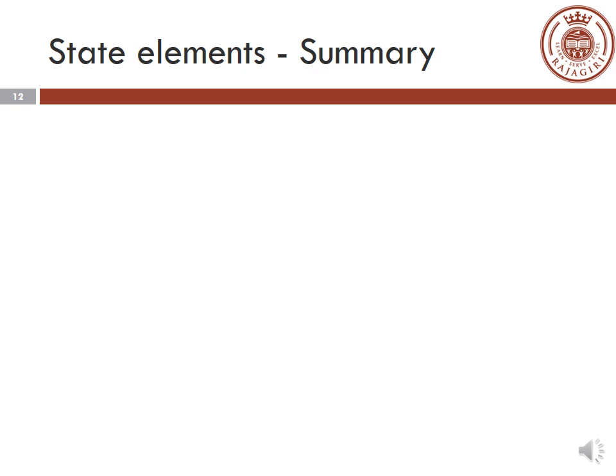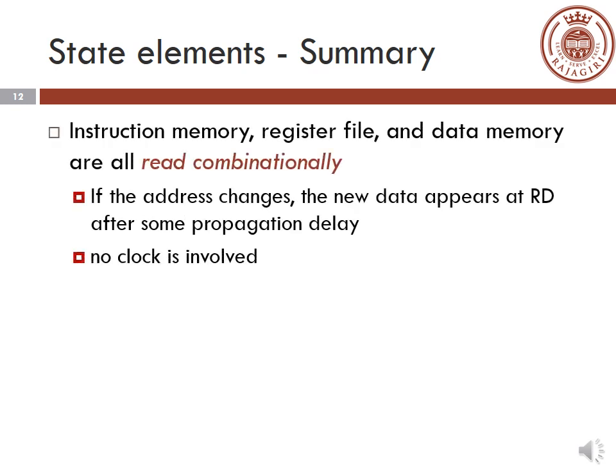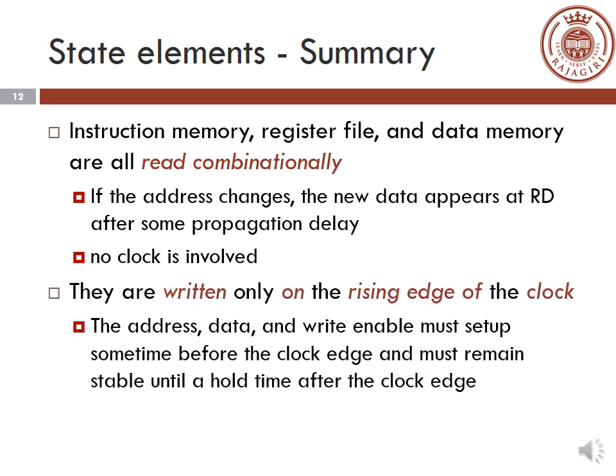Okay, so in summary, with respect to your state elements, the two important points that you need to understand are: for all the state elements, the write operation is sequential, that is, it is performed on the rising edge of the clock. Whereas your read operation is combinational.